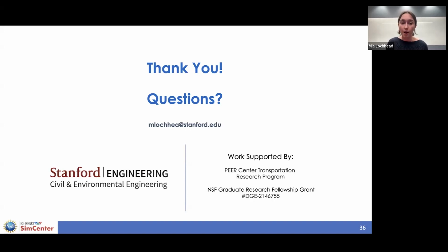So given the spectral shape in terms of SA ratio and then the duration, we want all of these to be realistic in terms of those parameters that we're expecting for California. And there's more extensive information on that ground motion selection in a paper that I'm happy to share with whoever asked that question. So no synthetic ground motions were used.